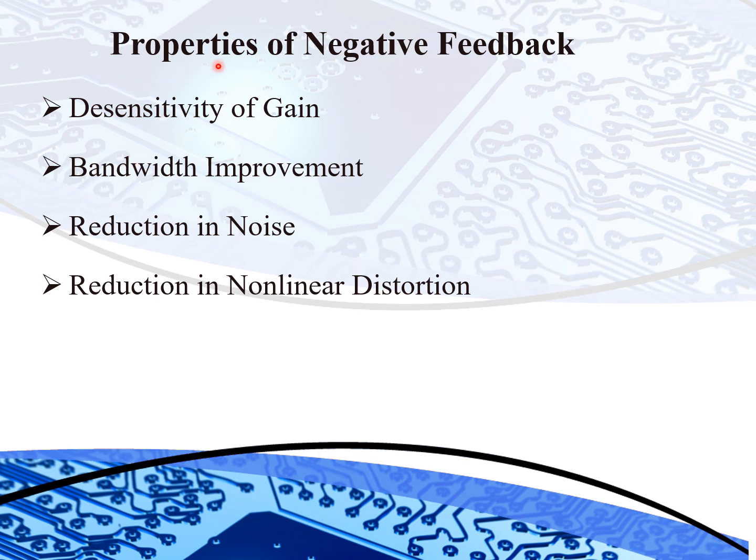We will discuss now the properties of negative feedback. The first property is the desensitivity of gain. Actually, the transfer gain of the amplifier is not constant and stable, as it depends upon many factors. Hence, we reduce the gain variations by introducing the negative feedback concept.